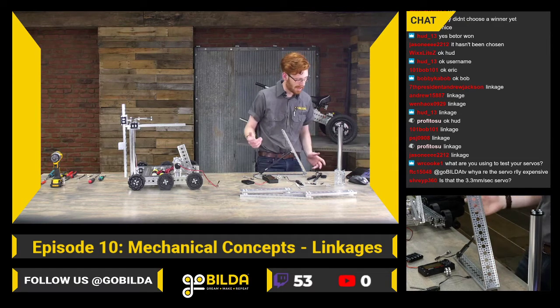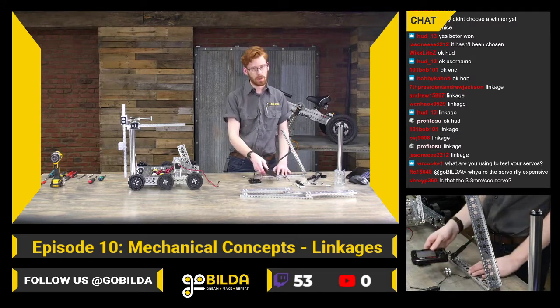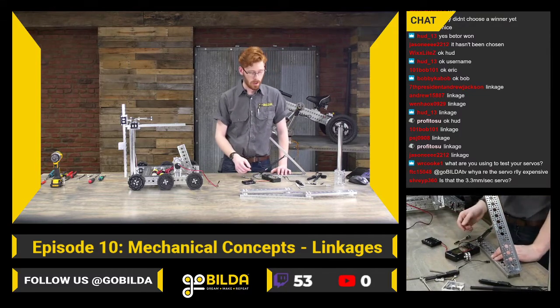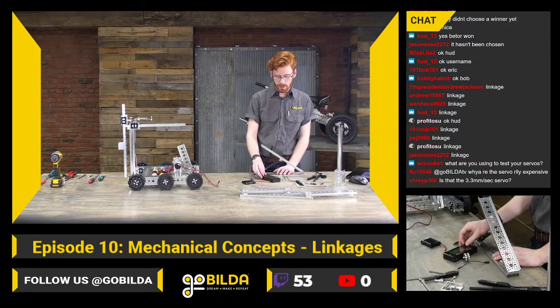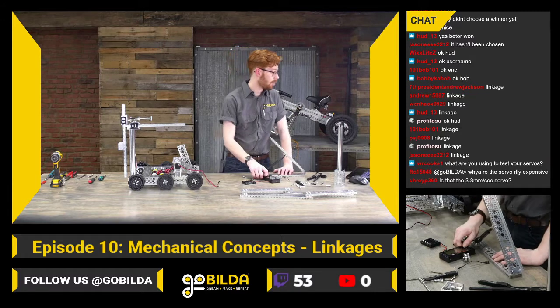But yeah. What are you using to test your servos? This is a Hitec HFP30. It's their servo programmer, and it's got some new firmware flashed on it to also be able to program these linear servos as well. It just works as a great servo tester for a lot of servos, and you can dial it into some really pretty precise microsecond level adjustments, which I like a lot.